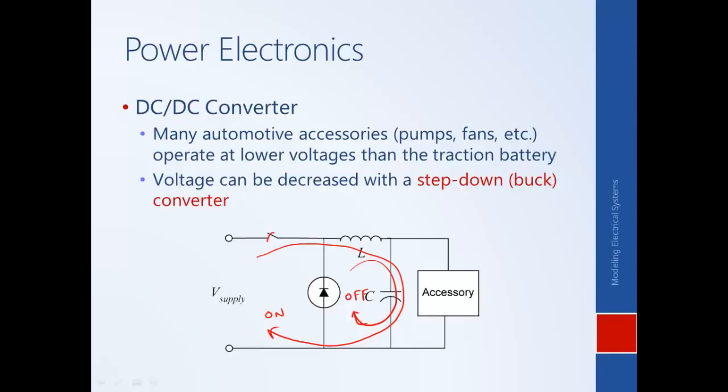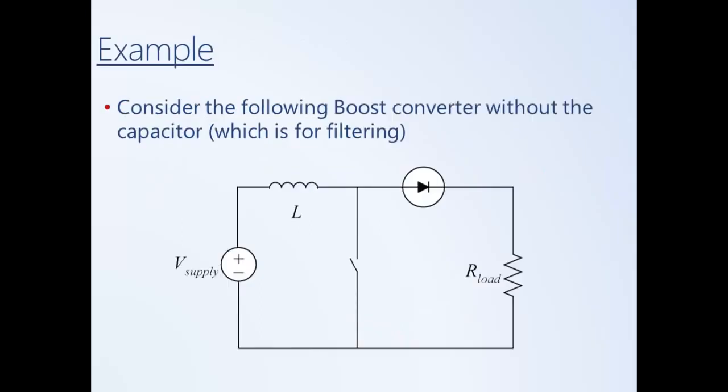At this point, we will go ahead and choose the boost converter and analyze it in more detail. So here's a boost converter where we've removed the capacitor that was here. I'll explain a little bit better what the purpose of that capacitor was, but in essence, it was there as a filter.